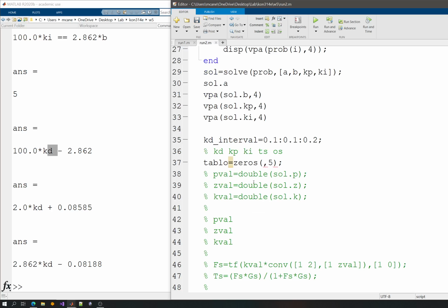Now, if you're writing code, keep it as simple as possible, since it is easy to debug. Now I will use the length because I have 0.1 and 0.2, which gives me only 2 points here in the finite subset of controllers. So I will have 2 rows, each row corresponding to each KD value. So I can just go ahead and calculate this by using KD interval.